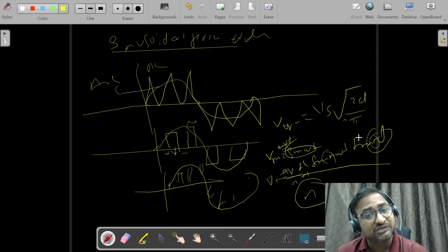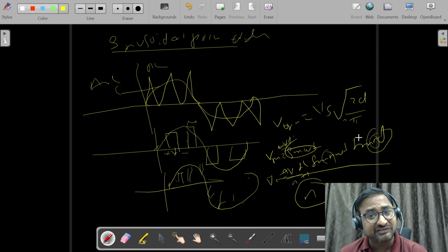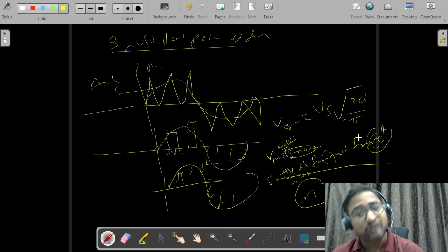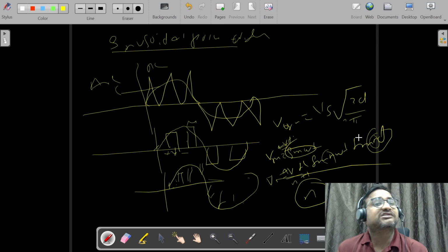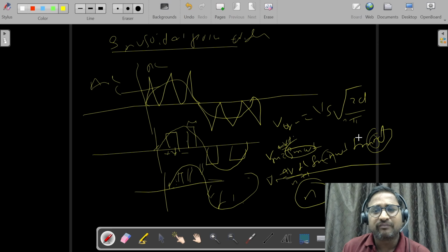After the production of harmonics, the frequency component increases. If frequency increases, eddy current losses and hysteresis losses increase, and IRMS, I mean current, also increases, by which copper losses also increase. When losses increase, we have given input as PI, so when there are more losses in the system, definitely output will be less than the input, by which my efficiency decreases and my heating effect also increases. In this way I explained the effect of harmonics.